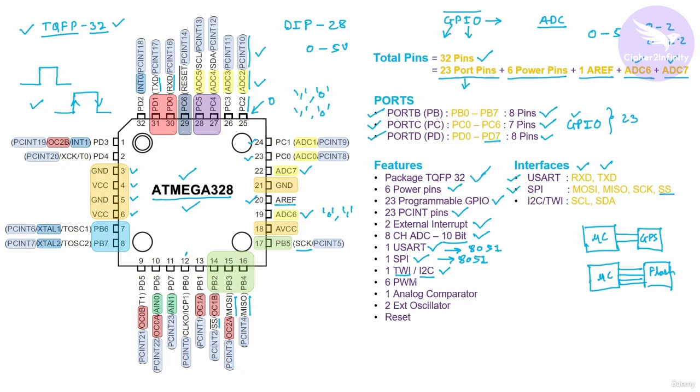Okay. But functionality-wise, or working-wise, they are almost the same. Again, in the 8051 controller, you will not find this I2C interface. Now these are actually the pins of the I2C interface: SCL, which stands for serial clock, and SDA, which stands for serial data. So like we discussed in the case of USART and SPI, again there will be some devices or some ICs which work on the I2C interface.